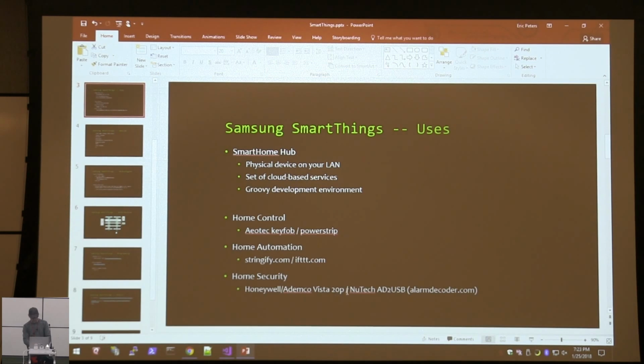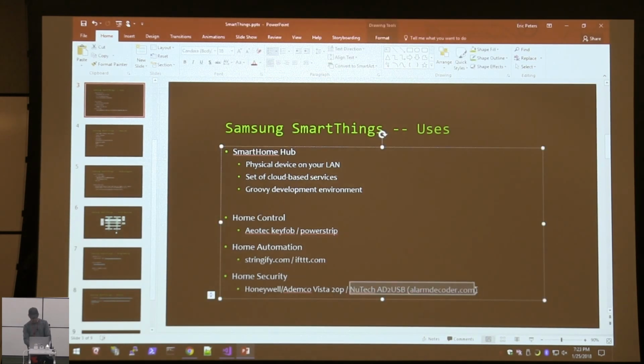Yeah, there's a device from alarmdecoder.com called the AD2USB, and the keypads all hook up with 4 wires, and so this thing has 4 wires, and you plug it into your circuit board here, and it pretends to be a keypad, and then it converts every signal that it receives to USB. Then you just literally log into it with a terminal or open up a COM port in your application, and so then you can communicate to your security system through the computer. That's why I'm running it on my local machine.